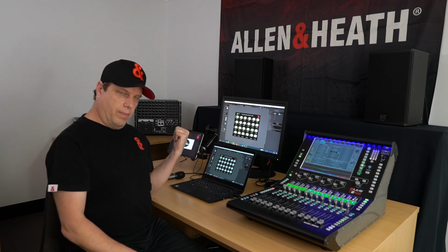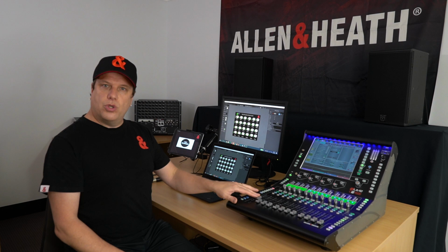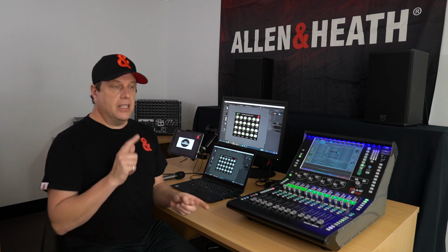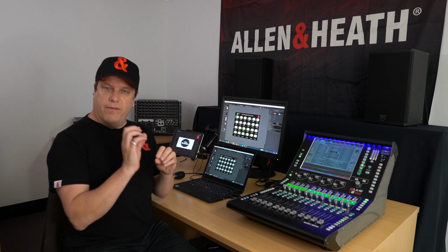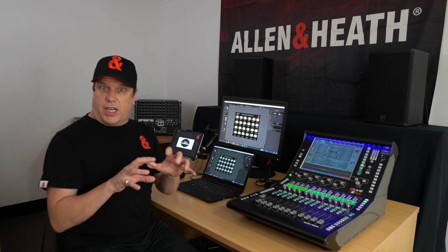So the same thing's happening to their PAFL bus. I've selected the vocal group to go to their speaker when they're not PAFLing something. So what that does for them is they can hear the vocal bus the whole time. So during the show, if I open a fader and the radio mic is crackling or something's not right, instantly the radio mic techs on the show know. I don't have to tell them.